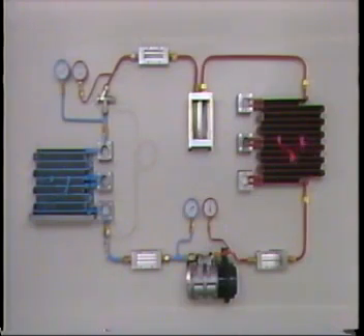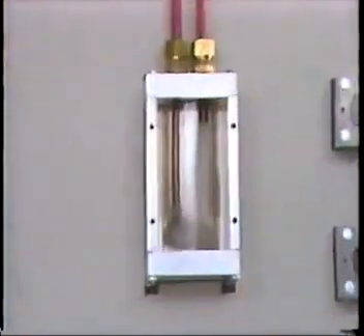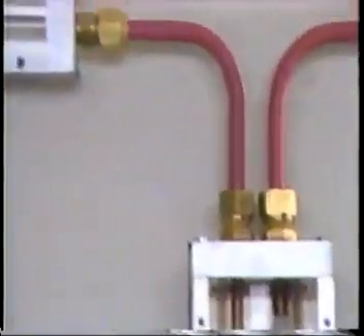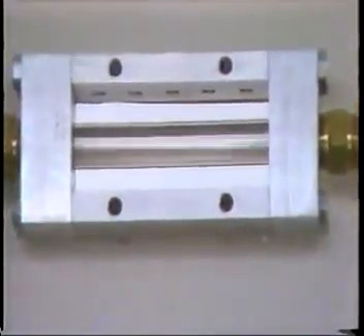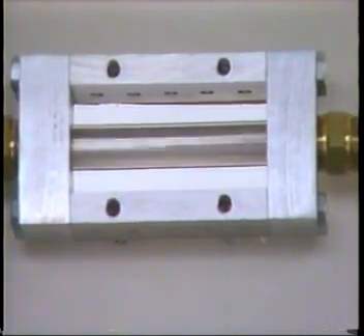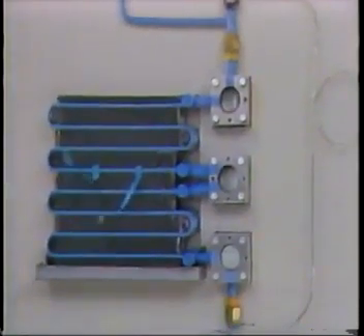You can easily imagine that the air conditioner's cooling power will be less if there is not enough refrigerant in the system. But why is this so? When the amount of refrigerant is less, there is naturally less refrigerant in the receiver and dryer unit. For this reason, much of the refrigerant is a gas when it reaches the expansion valve, as you see here. What happens in the evaporator then?